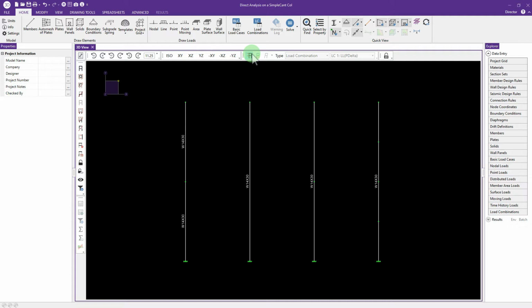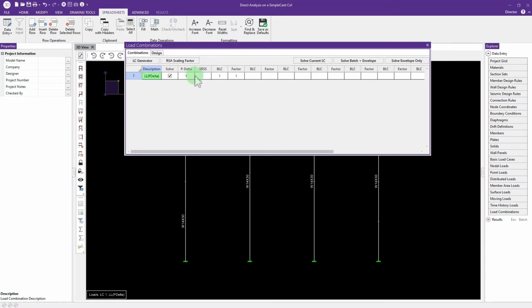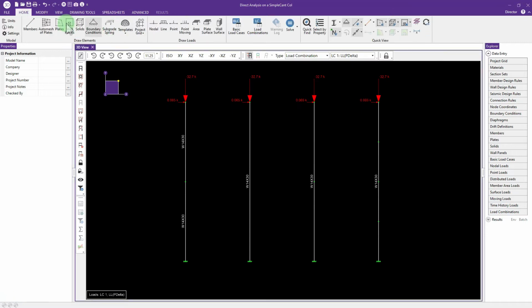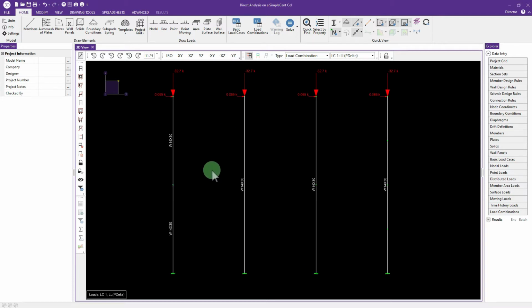All right, I'll go ahead and display the loads that are on the structure. Like I said, a horizontal and vertical load added together, and I am running a PDELTA analysis on this, and you can see from my load combination case that PDELTA is selected with that Y symbol within the load combination table. So this load case number 1, L PDELTA, includes that, and this will be the run with the nodal shear. Let me explain before I actually run it what I have in front of you.